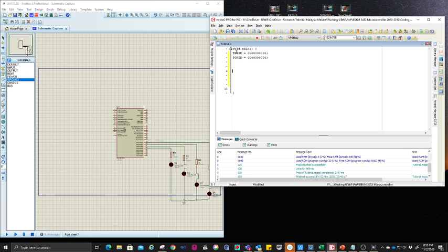And then you have the while(1) loop here. After this while(1), you must have a curly bracket like this. You have to have the head and tail to cover the body. So you can write inside it. Here, port D is equal to 0b, this is the last for RD0, RD1. It's going to be like this: 0, 0, 0, 0, 1, 1, 1, 1.